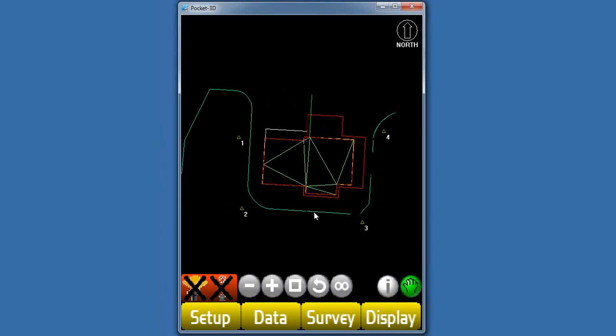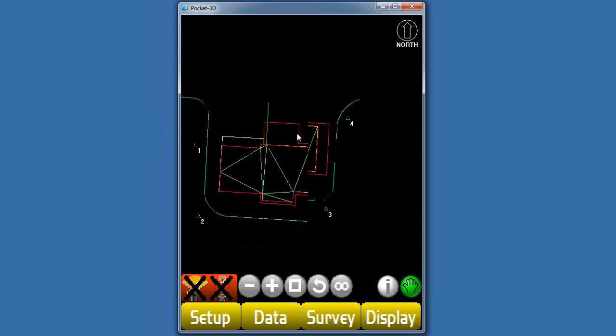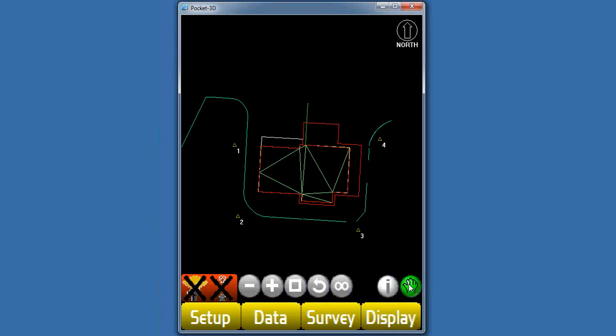We've got what looks like a little contour line that kind of goes around our parking lot. We've got pad lines that show up around our pad that kind of define where the pad is. And you can see the surface, the triangulation network, that is the data that is represented by the vertical component of the surface in that pad area. We've still got our control points. We can move around. You can see we're in pan mode.